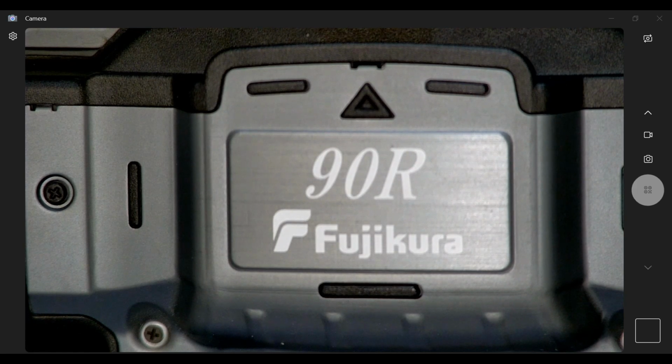That's correct, Mega. When we first started in the industry, we were more concerned, is it a single mode fiber, is it a multi-mode fiber? We really were talking about the glass composition, what type of dopants were present in the optical fiber. Now we're getting into some mechanical structures of the assembly itself. What's the coating diameter? Is it 200? Is it 250? What is the rollable ribbon structure? What is the fixed matrix structure? These things are critical to understand so that we provide you with the correct fiber holder V grooves in order to give you what I call good, better, best, the best operational situation that you can have in the field environment.